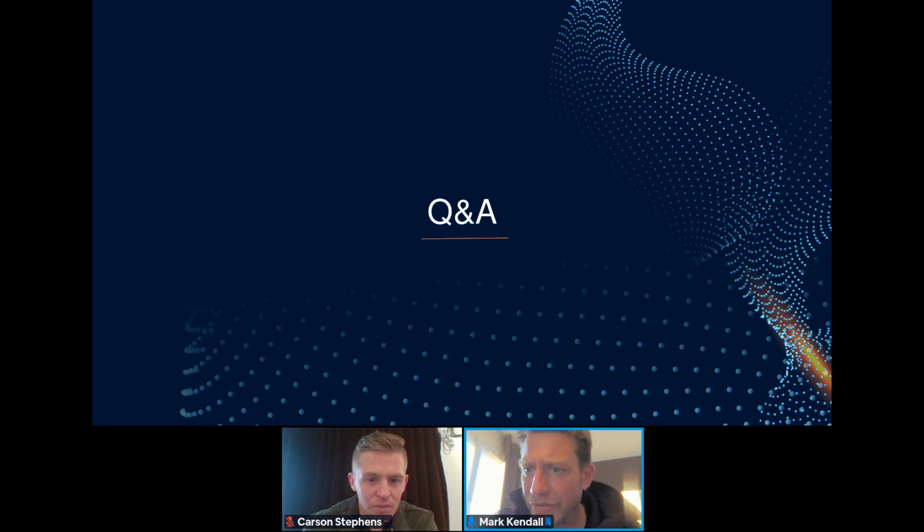There is also one question regarding, is Fike Blue a clean agent? No, it's not. It's not a chemical agent at all. It's not like Novec or FK-5-1-12. It's not like FM-200. It's very different in its makeup.